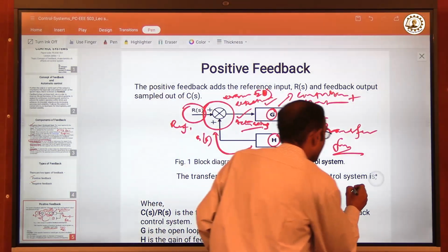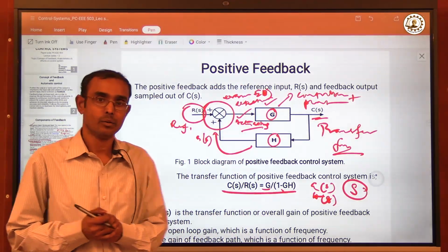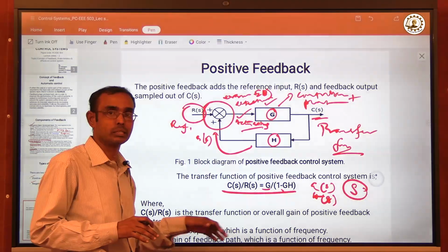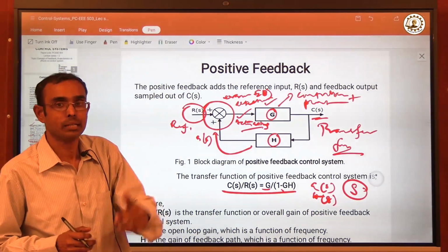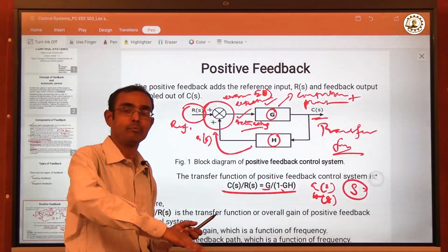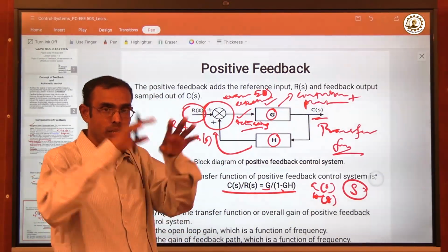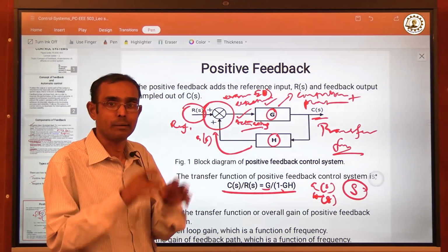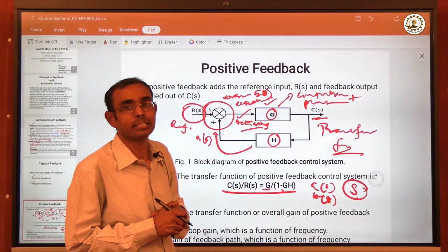So this S is basically the Laplace transform parameter we use to represent the system equations in a time domain form, and while we use the Laplace transform to convert the time domain form into the Laplace domain, in the simple linear algebraic equation, everything comes as a function of this S. This S is called complex frequency.